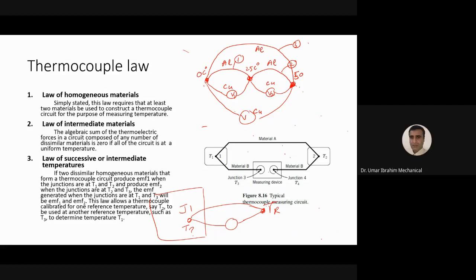So what I'm saying is that in a thermocouple, the output is of course voltage, and you can convert that voltage output for any type of thermocouple into delta T. Once you get delta T, you need to find out the unknown junction temperature, or the measuring junction temperature value.